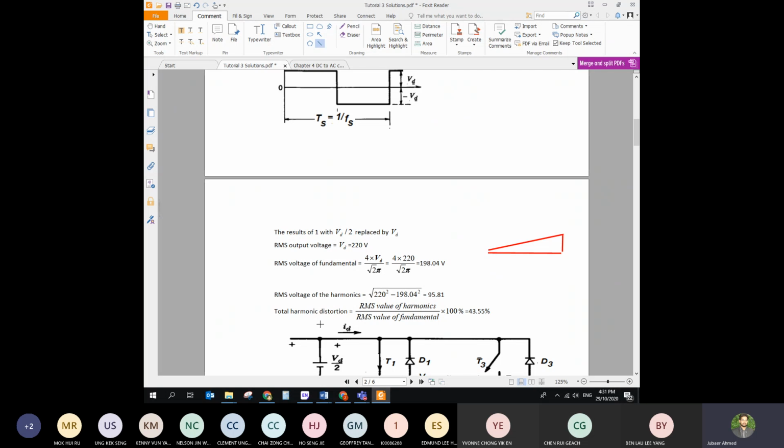The higher the THD is, the higher the loss from the harmonics, because when we convert from DC to AC, our AC devices are supposed to operate at a fundamental frequency, like our ceiling fan or some other devices which are designed to operate at pure AC, not for harmonics-based AC. So when there are multiple components coming, they are going to create disturbance within the magnetic field of the components. If you operate a motor, say your blender or washing machine, these harmonics are going to create big trouble inside the motor magnetic field, and it is going to reduce the lifespan of your electrical motors. That's why in our normal houses we never supply this power electronics based